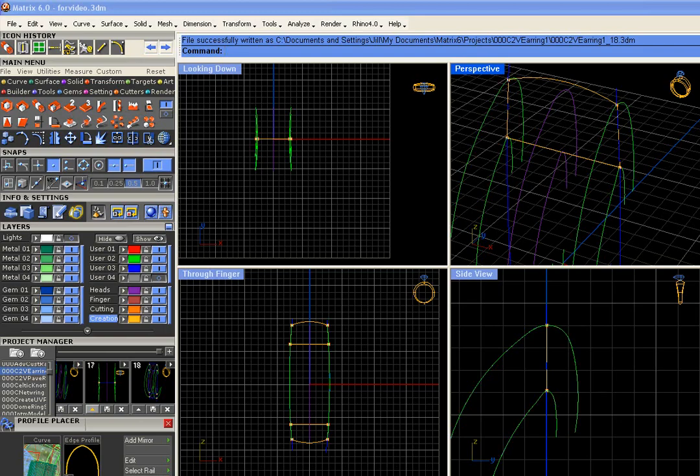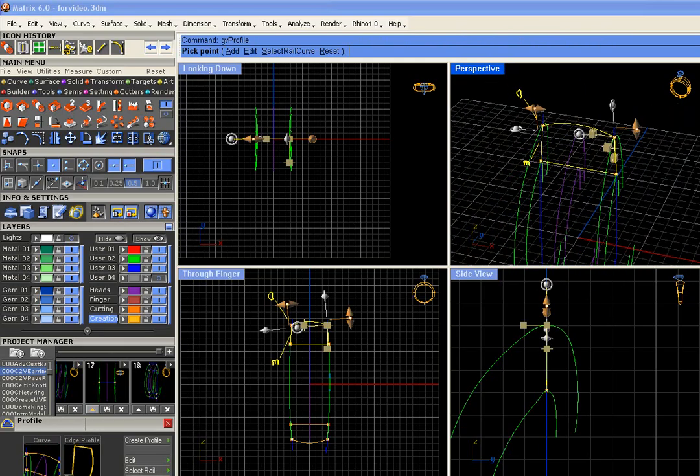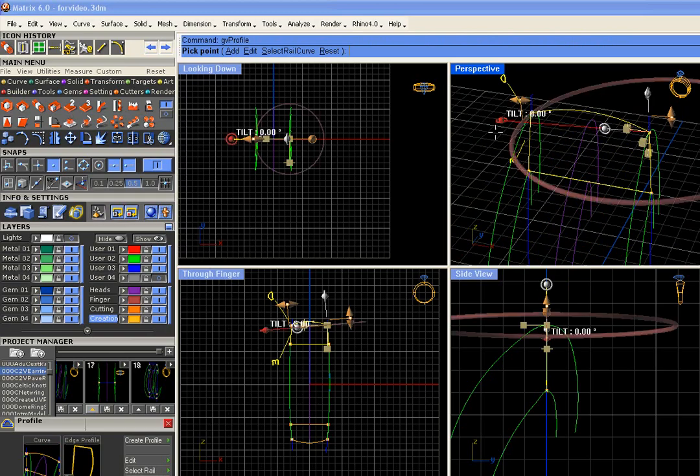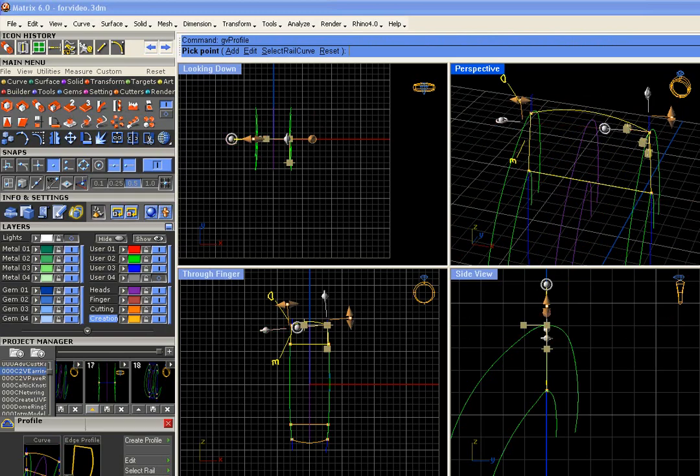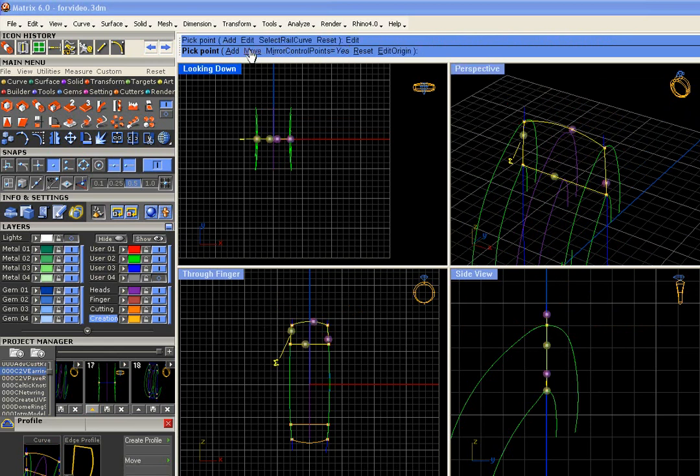So to associate it with that center rail, we select it, hit F6, and start up MSR. Okay, now notice your handles are all wacky. It thinks somewhere over here is the origin, maybe over here. We can fix that. Go to the edit command, use edit origin, and there's our origin, someplace bizarre. Stick him right at the midpoint, and go back to move.